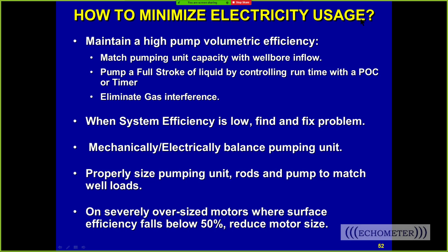So what do you do to minimize your electric usage? Well, the number one thing is to maintain a full pump. You need to match your pumping capacity with your wellbore inflow. If you're pumped off, then consider a variable speed drive, a pump off controller, or timer. If you have gas interference, run a properly sized gas separator at sufficient capacity.